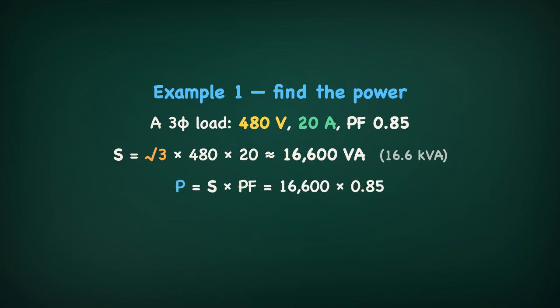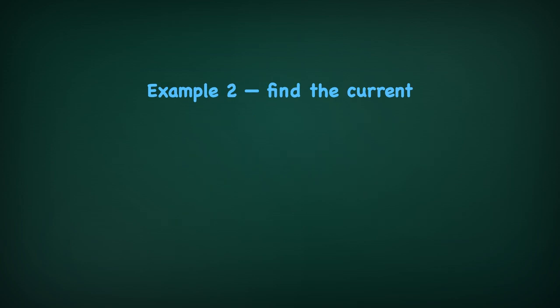Now for real power, multiply by the power factor. 16,600 times 0.85. That's about 14,100 watts, or 14.1 kilowatts. That's the actual work being done.